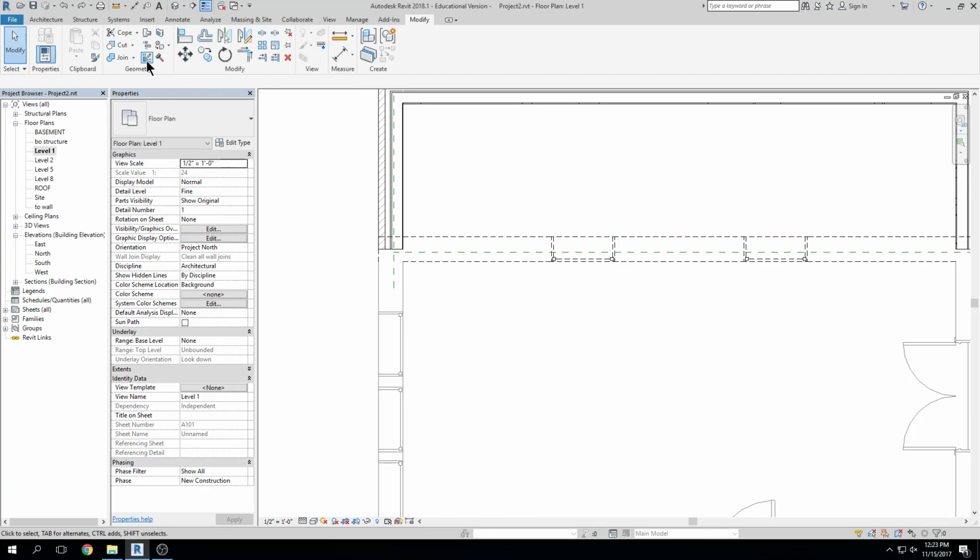So I'm going to click on wall join. I feel like this tool is really clunky. I click on wall join, I hover over the wall join I'm concerned about and I click. And immediately Revit defines the 3 walls that are working together. And I'm going to choose disallow join. I could also have chosen a different joining configuration like mitering. You see how that changed? And square off. So I can change the way that these join, or I can choose to disallow the join.